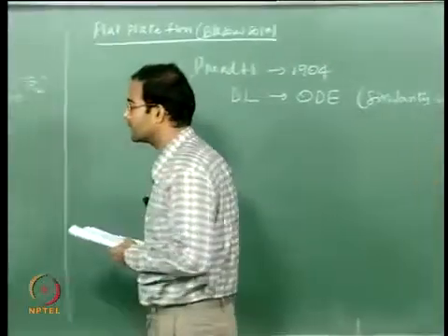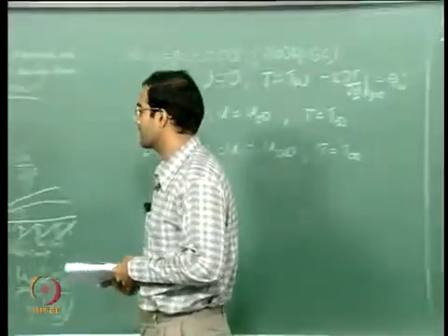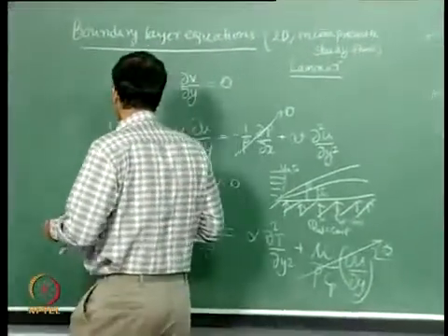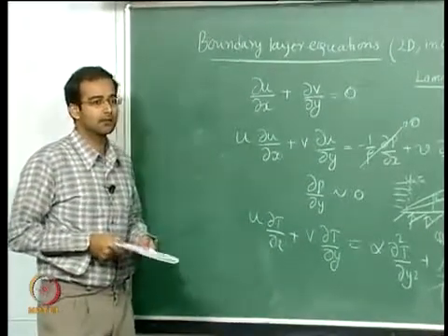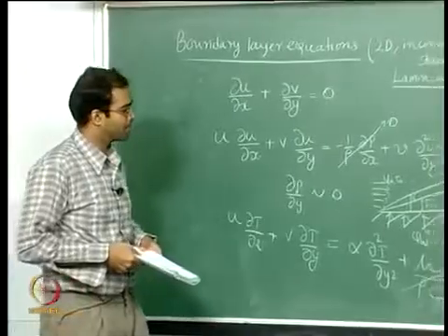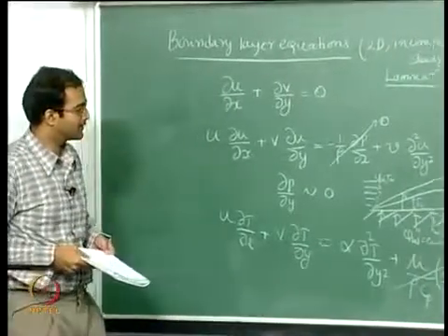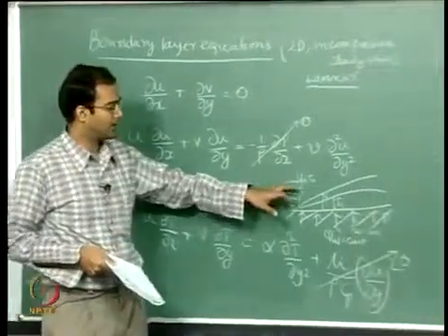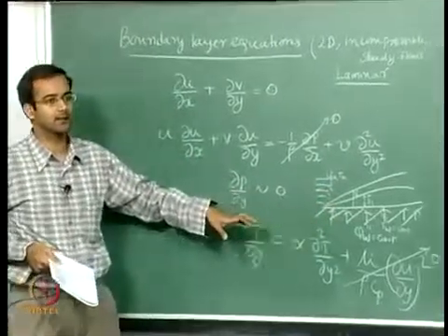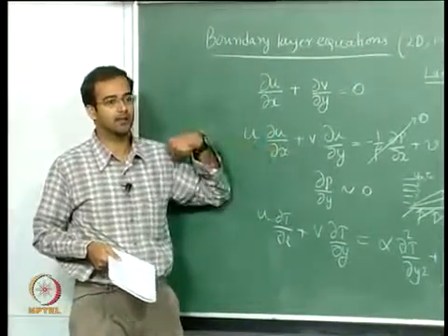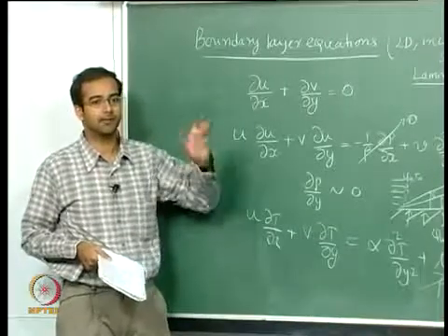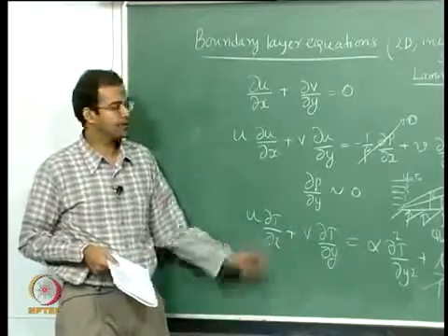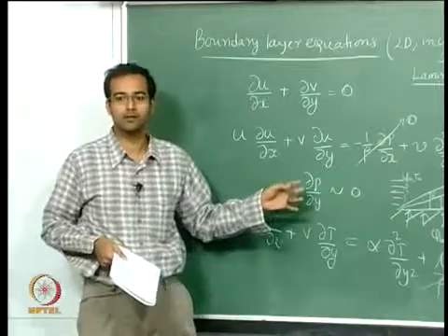It is a great concept that he introduced, that all the time we don't have to go for a numerical solution. If you are clever enough to see some relationship between the non-dimensional flow velocity, the property, and the coordinate it depends on, and cast them in a correct form, you can transform the PDE directly into an ODE.